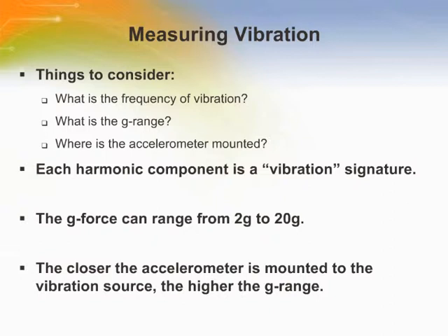For measuring vibration, the first thing to consider is the frequency of the vibration. This will determine the type of roll-off frequency for the different devices that Freescale offers. The second thing to consider is the G range. Depending on the vibration measured or the strength of the motor, there will be a different type of G range.